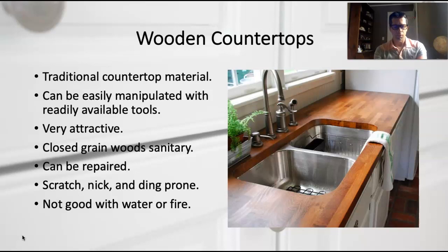I've talked to a few people in the countertop industry who said that for a while, maple countertops were really hot and everybody was putting maple countertops in. And then 3 years later, they're tearing them all out because it's all molding around the sink. So I'm not entirely sure how the installation occurred, but I would say it would be a good idea to really carefully seal the backside of that countertop and assume that water is going to get underneath that countertop, between the sink and the countertop, regardless of what kind of caulking you used.